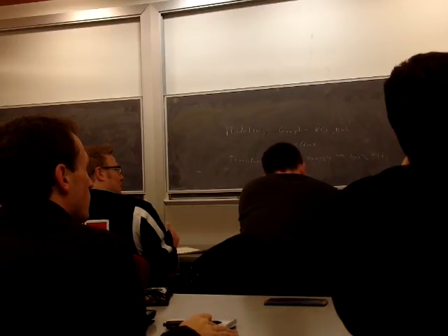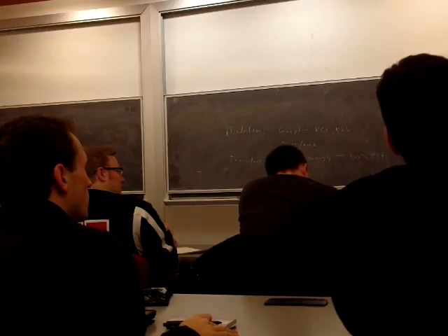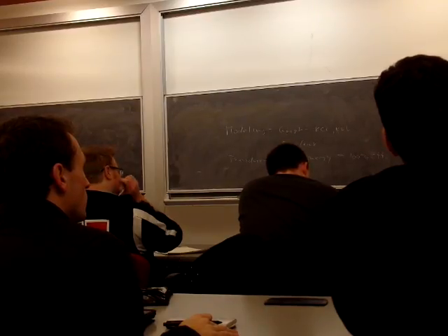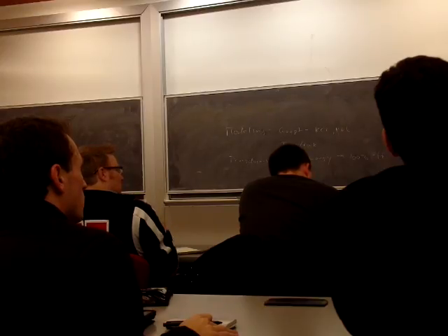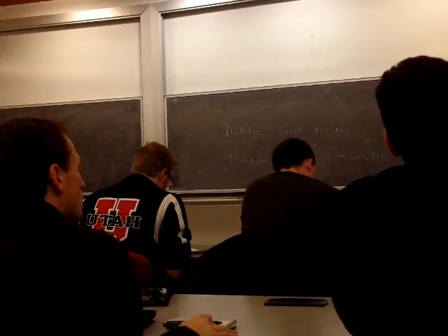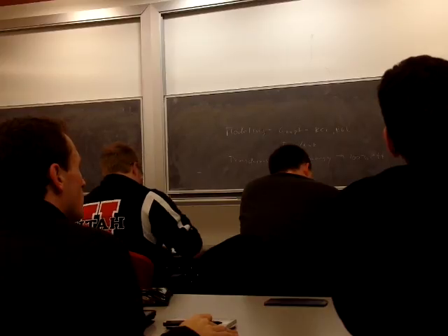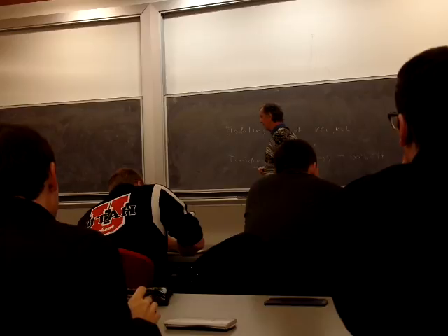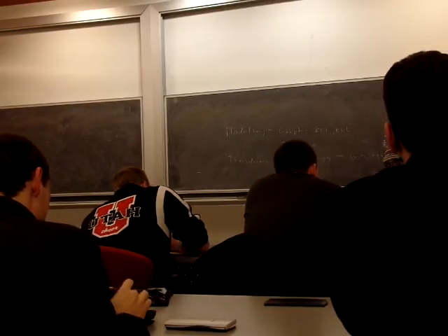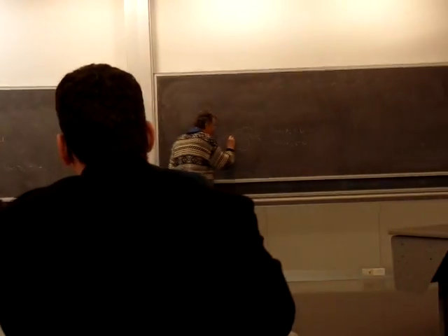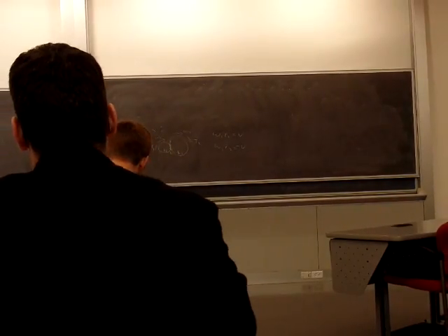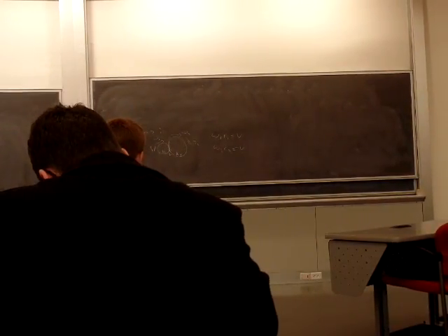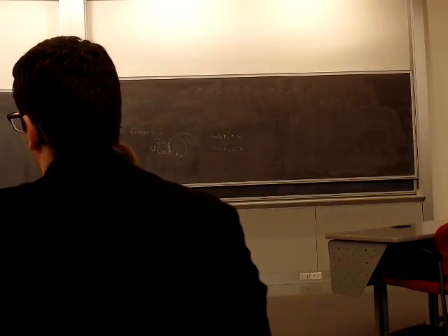It's number of teeth of what? Per unit diameter of the pitch circle. What's a pitch circle? The circle where they touch, the tangent circle of the touching gears, halfway between the teeth. Now, what I've drawn here is really on the pitch surface. This is the part that's tangent. So the diametral pitch has to be the same in each gear.